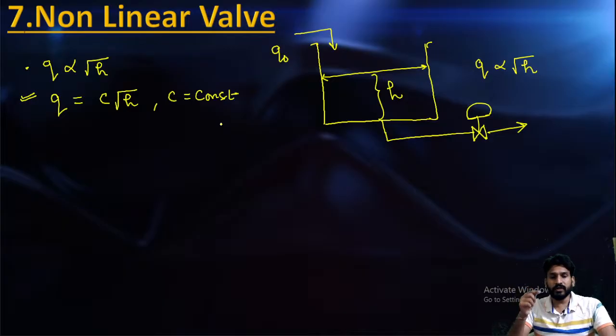So we cannot put any non-linear term in that differential equation. I have to put only linear terms. So I have to linearize this function, this under root h. After the linearization, I will put that value into the first order differential equation, and I will follow the same steps.